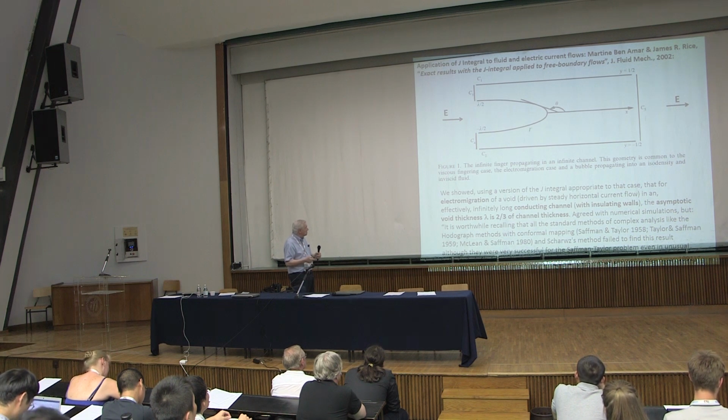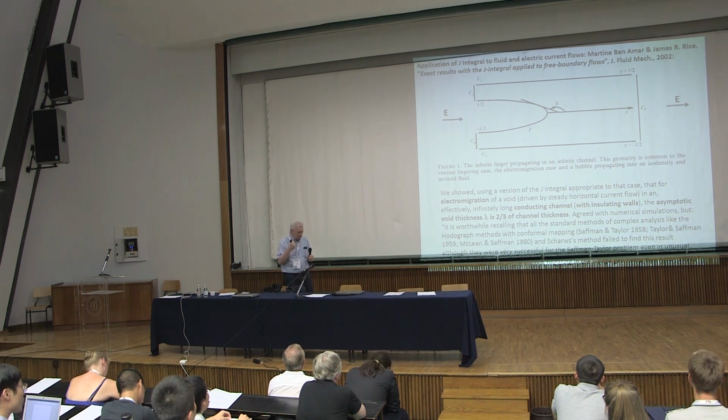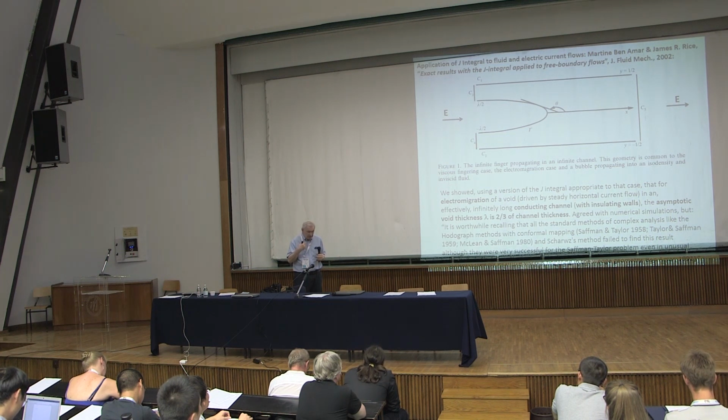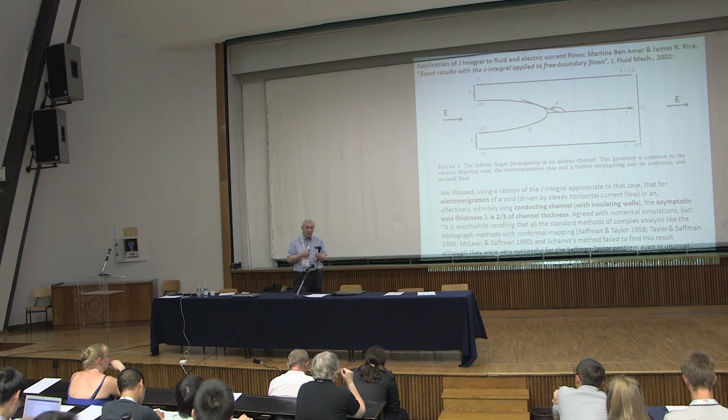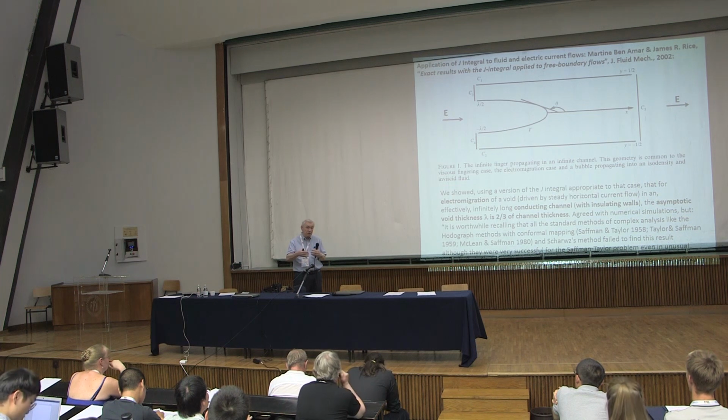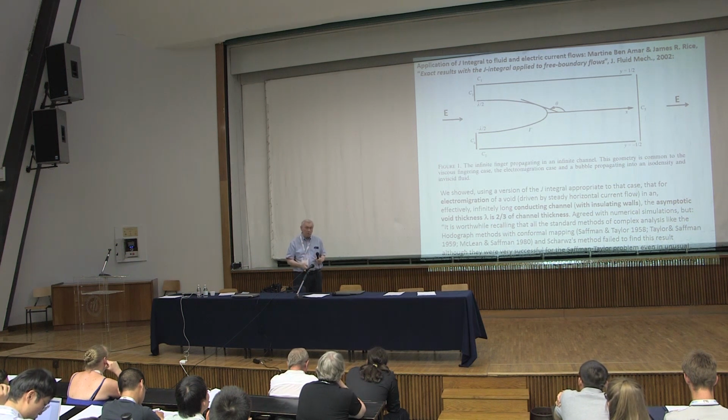Now, electromigration is not quite a fluid flow, but it's the idea that if you have a complex alloy and you're sending an electric current through it, as the current moves, you put different atomic level forces on different atoms in the crystal, and that causes a drift of material. That's called electromigration. And it causes voids in conductors to move in time as current flows.